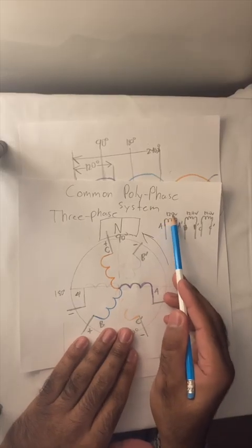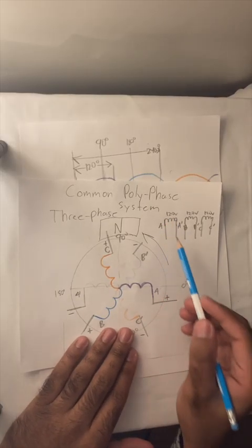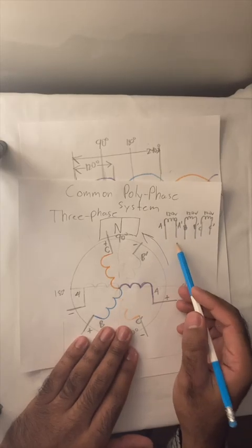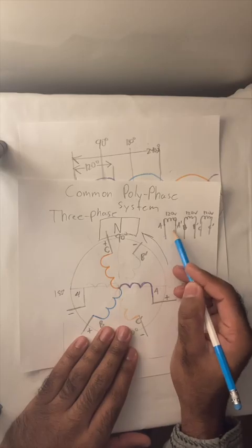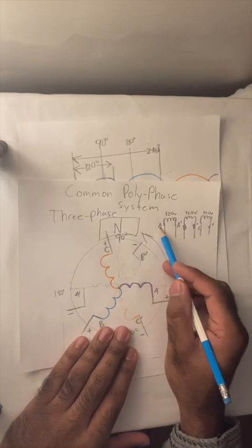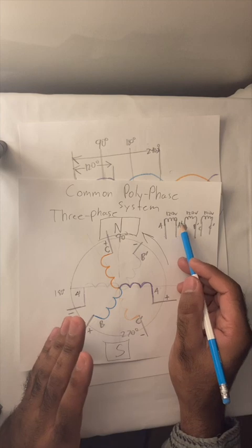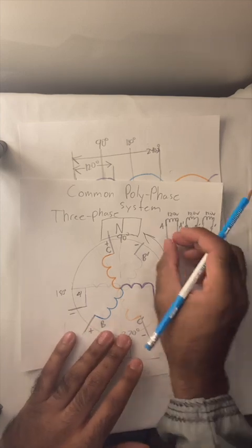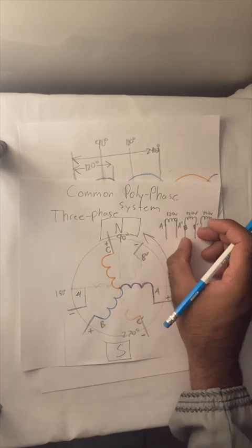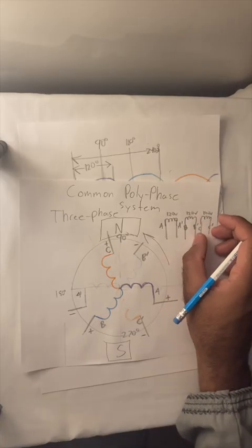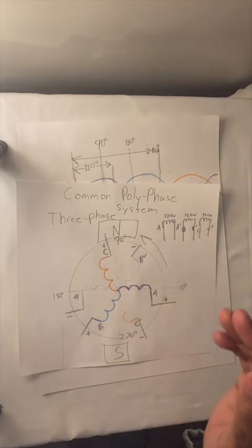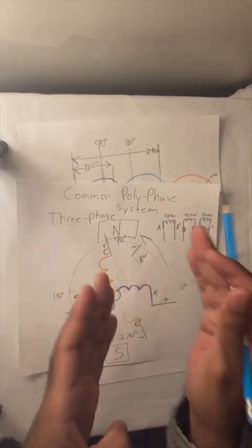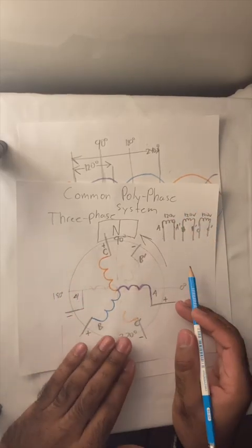So referring back to the RMS, we have 120 volts. So that means that between each of these leads, there's going to be 120, 120. So between line A and line A prime, we have 120. B and B prime, 120. C and C prime, because these are testing across. This is phase voltage.